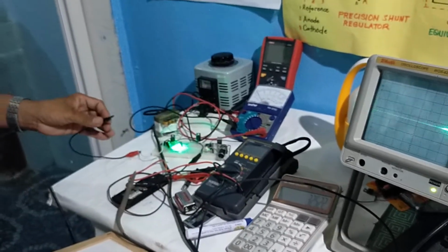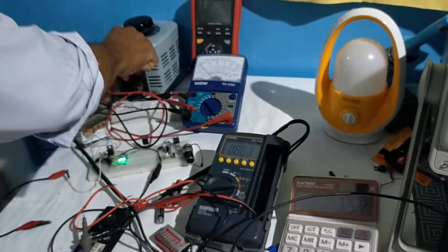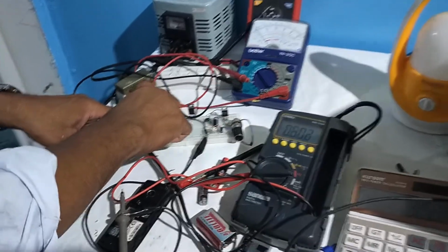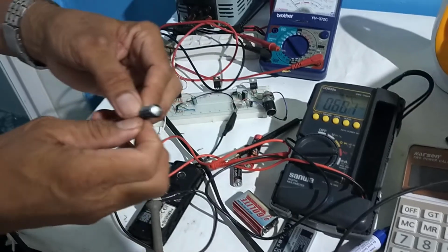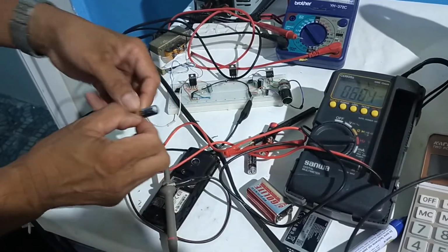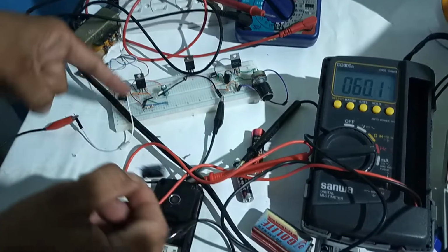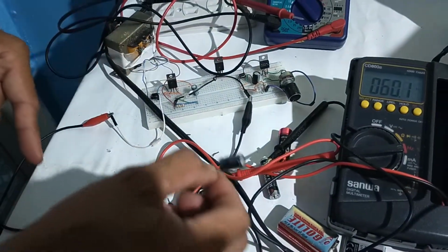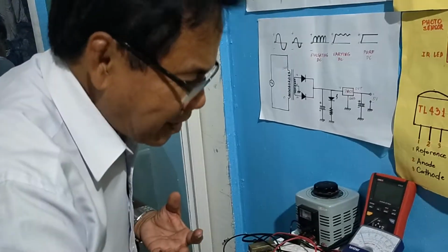Sorry, there's something wrong. Probably the capacitor was inverted actually. We mistakenly connected the capacitor because this side here at the input of this IC is positive. We happen to connect the negative side. That is a very good experience, class. There is an evidence that once an electrolytic capacitor, which is polarized, is inverted in a circuit, it will explode. Okay? Okay, we will change this one.